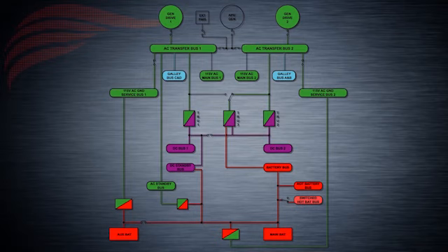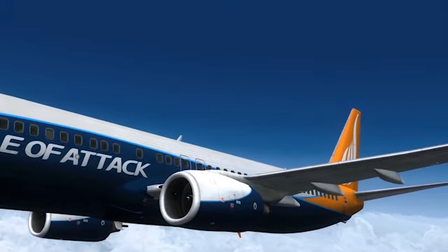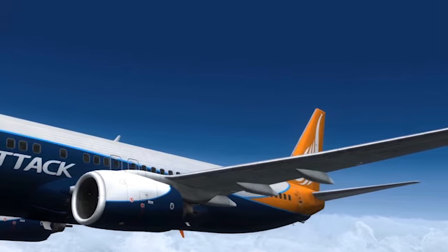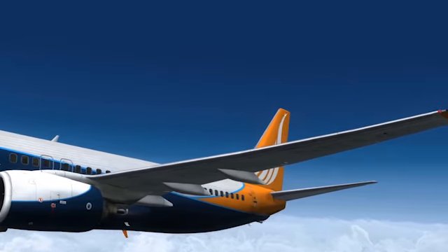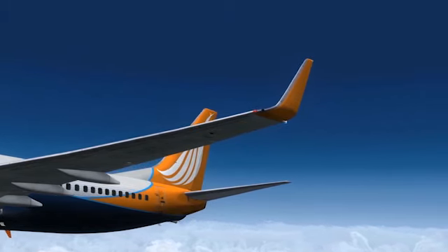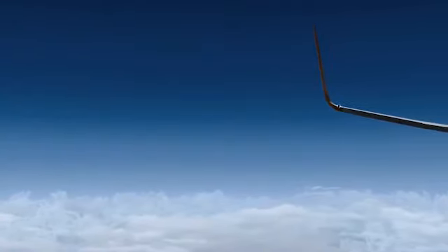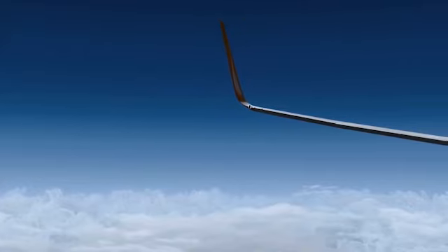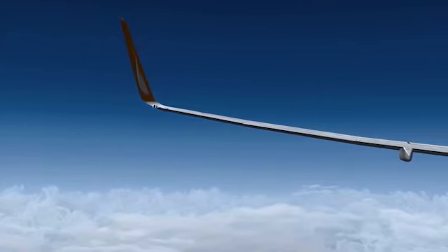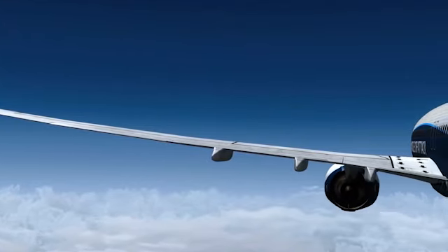Both batteries are 48 ampere and 24-volt DC power sources. In very simple terms, the battery's connection logic is the following. The main battery normally only supplies power for APU starting, but is a standby power source when all other power sources are inoperative, such as during a complete loss of AC power if both engines are shut down in flight. We all know that the chances of this occurring are minimal. However, the redundancy must still be built in to make the systems more reliable and dependable.